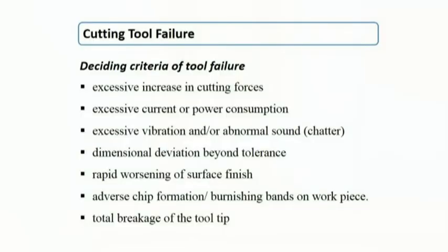Another most important criterion to decide the performance of your cutting tool is the tolerances that you are achieving. Suppose initially you are achieving good tolerances as you require, but after some time, if you are not able to achieve those dimensional tolerances, then it indicates that there is something wrong with your tool.